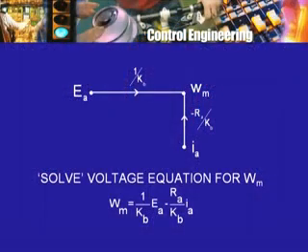However, since I have already written down an equation in which omega m is the sum, from the second equation I cannot solve for omega m and express that as another sum. There is nothing wrong with writing that equation, but the way one draws and interprets the signal flow graph, this cannot be done. This is the one important condition that one must adhere to. So we can solve it for IA, because in fact it is very easy to solve for IA. Just divide through by KT.